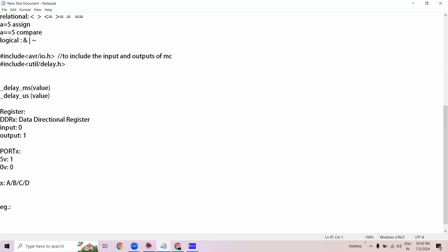So suppose you have port B7. Port B7 we have to write on the MSB side, and port B0 we have to write on the LSB side. We have a total of 8 pins starting from 0 to 7. So I'm writing MSB to LSB, port B7, port B6, port B5. Why am I telling you this MSB side and LSB side? Because whenever we write the program, PB7 always comes to the left side and PB0 always comes to the right side. So accordingly, I'm writing the code here. So as I said, we have 8 pins, 7, 6, 5, 4, 3, 2, 1 and PB0.